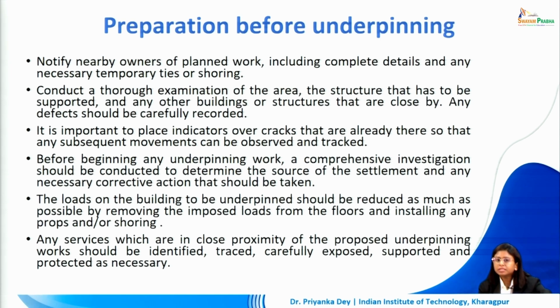The loads on the building to be underpinned should be reduced. So let's say not everything in the upper superstructure of the building can be removed. Many of it is permanent, and the self weight of the walls and slabs and structural members is not something we can alter. But there are a lot of other loads, live loads that are placed on the building which we can remove. So that additional imposed load we can definitely get rid of from the upper floors of the building while we are doing the propping or the shoring in the building, to ensure that not a lot of additional unnecessary support is created on this foundation while we are trying to make changes in it.